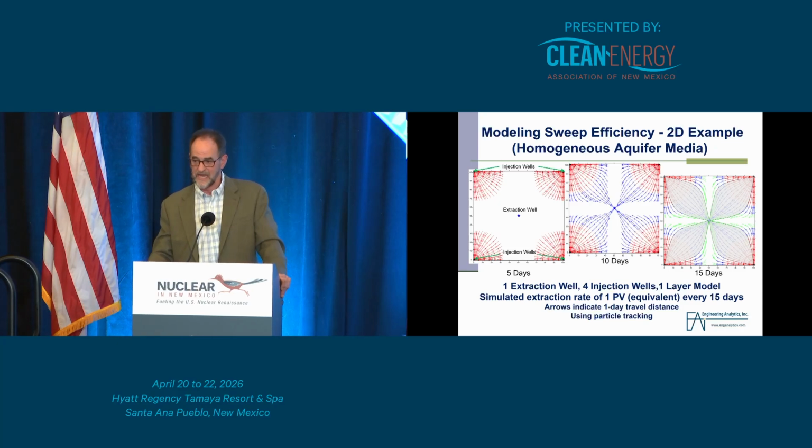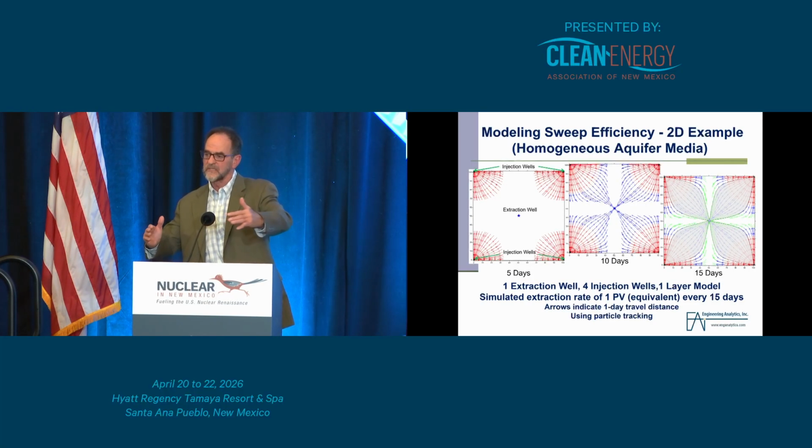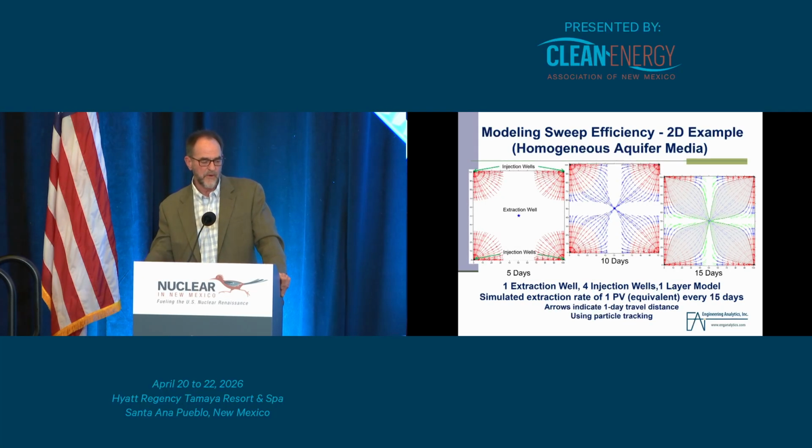Well, you can see, now we've taken out 1 pore volume, it's been 15 days, and yet a good portion of that area hasn't even been contacted by the injectate yet. Some of it has been contacted, but it hasn't made it to the extraction well yet. Obviously, if I keep running the simulation over time, those traces that you see outside the gray area eventually are going to get pulled into the extraction well and we'll recover the uranium in them.